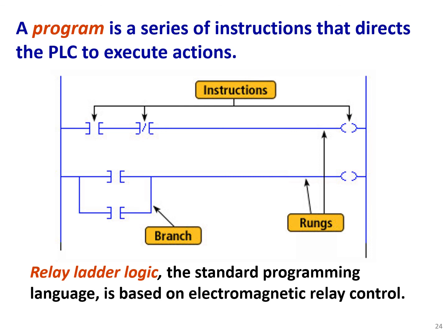Relay ladder logic, the standard programming language, is based on electromagnetic relay control. So the ladder logic program is the most commonly used program in PLCs, and it follows the same logic as connecting relays by wires. So instead of wiring and rewiring real relays, we just connect and disconnect those relays inside the program.